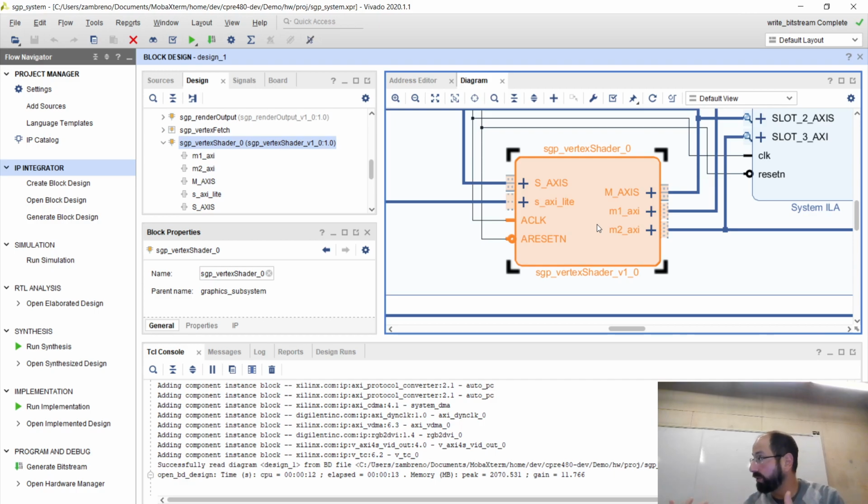But the IP cores you're designing are going to have that. They're going to have an AXI Lite interface for things like configuration and status registers. It's going to have stream interfaces, as we'll talk about, because we want to FIFO data around in our system. And it's going to have full-fledged AXI memory-mapped interfaces if that IP core needs to read or write from some block of memory somewhere in our system. In this case, this core has 5 such interfaces associated with it.